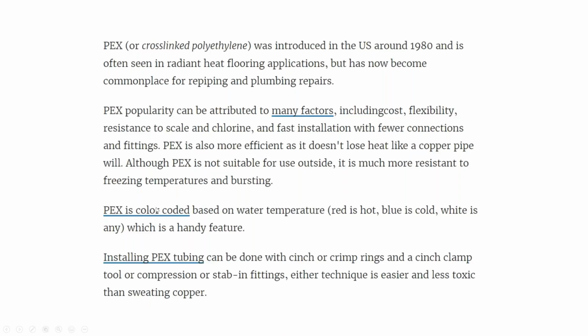So PEX is color coded. Red is for hot, blue is for cold, white is for either. It can be done with a cinch or crimp rings. It's much easier than it is to sweat copper and to solder all that together.